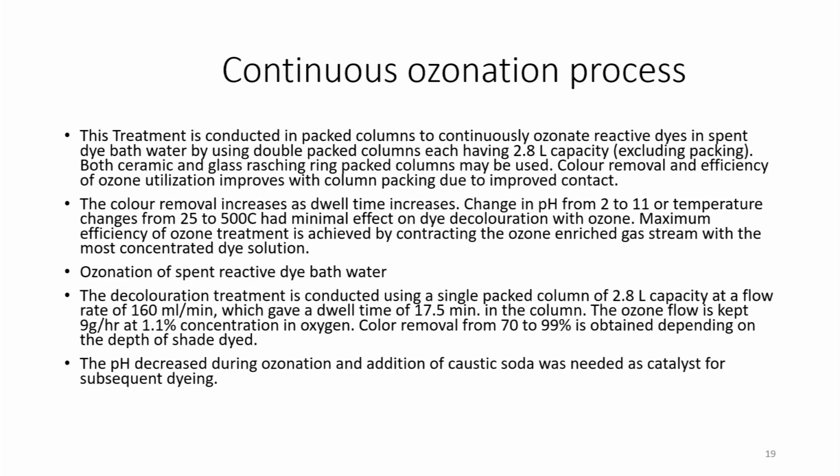Both ceramic and glass raschig ring packed columns can be used. Color removal and efficiency of ozone utilization improve with column packing due to improved contact.